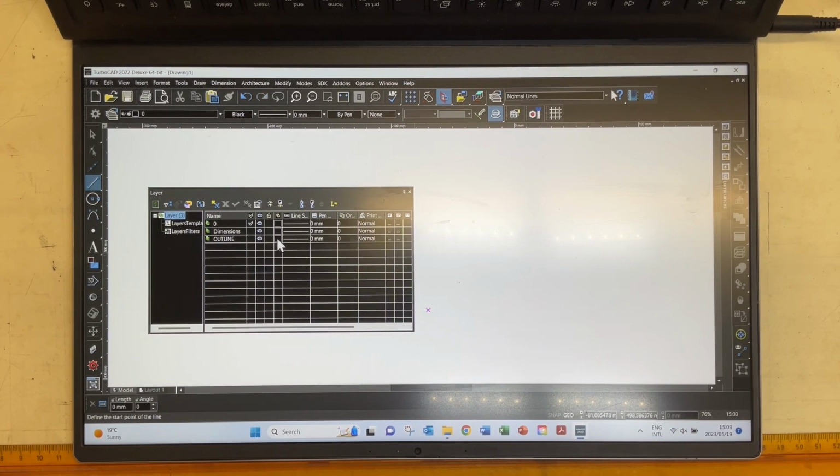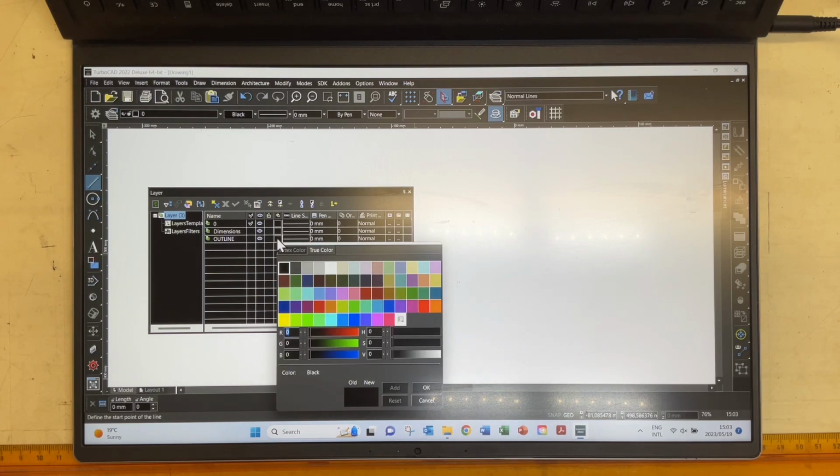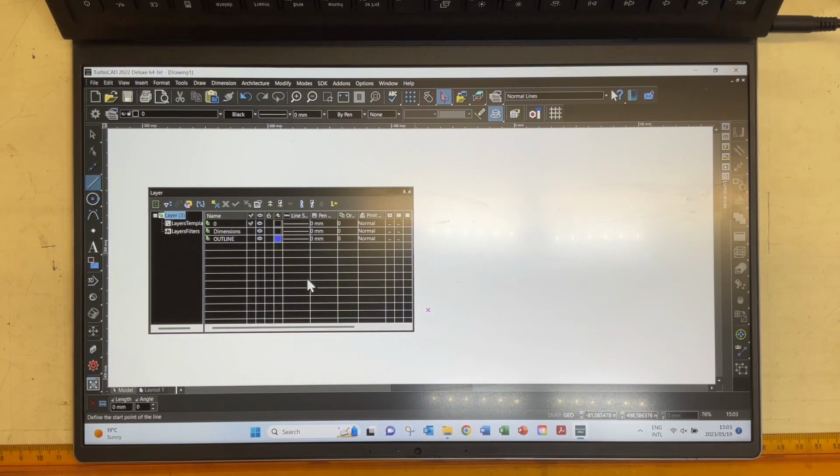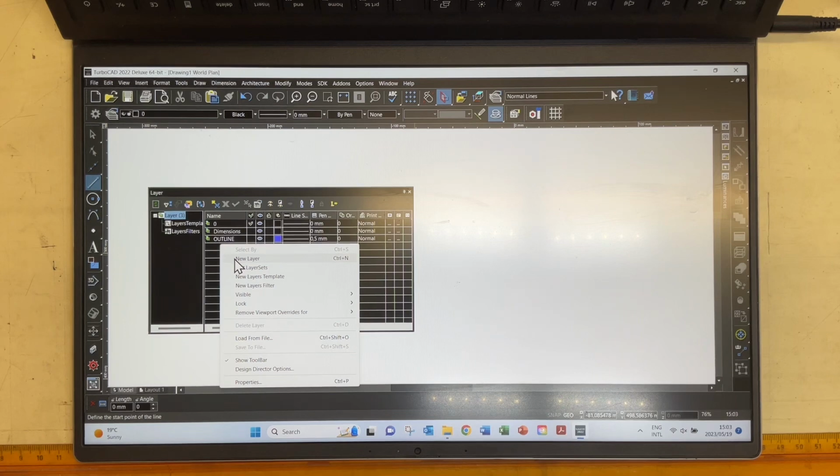You're going to change the color of that line by clicking on that little block over there. I like to come down over here to where it says medium slate blue. It just is a very nice color to use. I then come across here, you can see that the line that is being used is a straight line. The next little block in line there says 0 millimeters. Now I want a 0.5 millimeter line. Okay, 0.5 millimeter line.